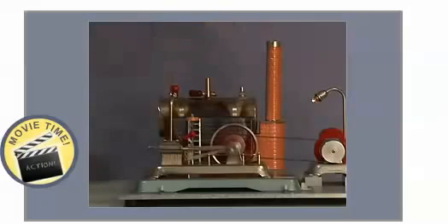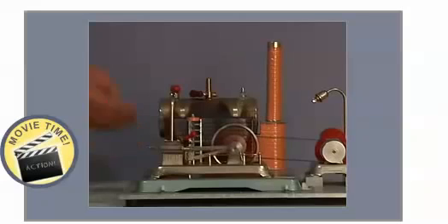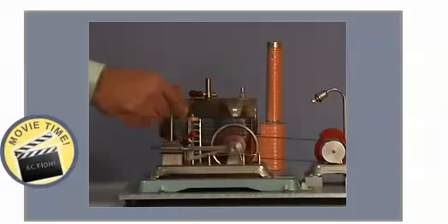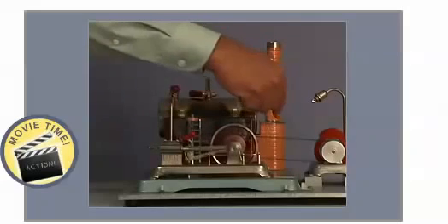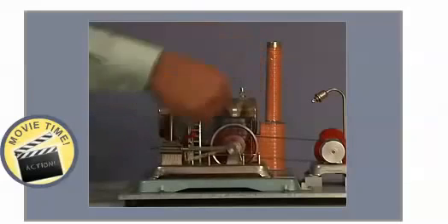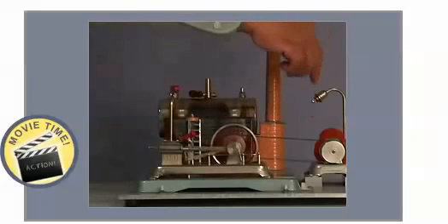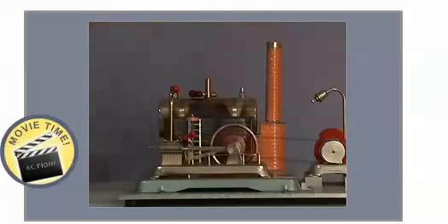So the efficiency of this power plant is only 35%. 90% of what we put in is coming into the turbine here, and this turbine is putting out only 40% of this 90, which is about 36 units, and this generator is turning that into about 35 units of electricity. So overall, when we start our business with 100, we're coming out with 35 units of electricity. So the overall efficiency is only 35%.